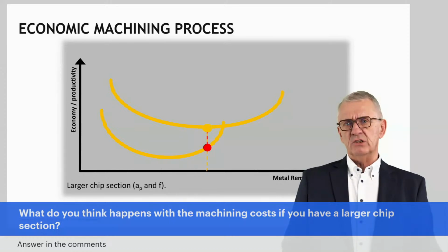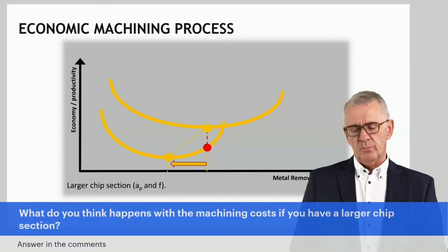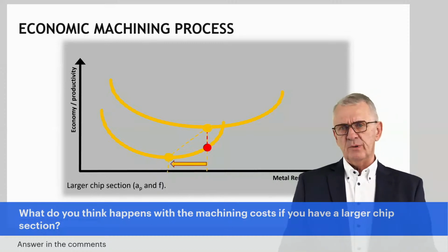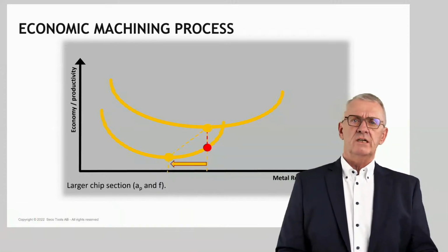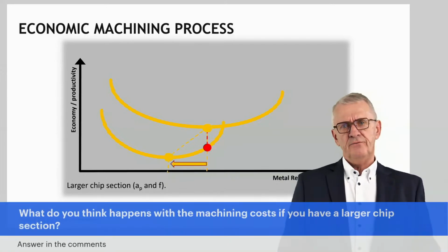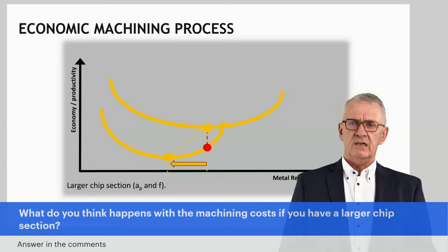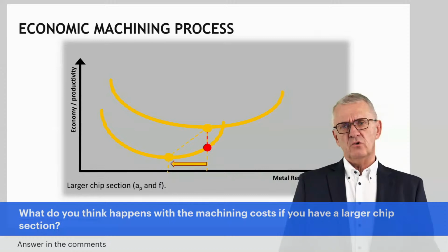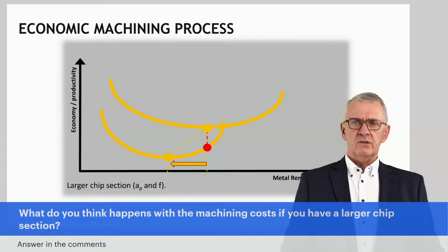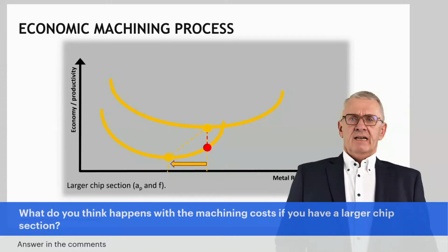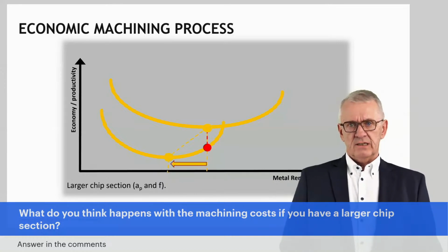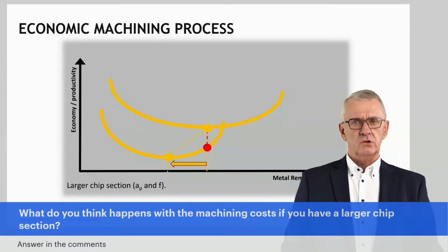And you as a machinist, you can make the advantage even bigger by compensating bigger depths of cuts and feeds with lower cutting speeds. So if you start to think in terms, and now we are basically into machining strategy thinking, if you can find combinations of tools and strategies that give you the possibility to increase feeds, to increase depths of cut, and combine that with lower cutting speeds, that's going to give you serious possibilities to reduce costs.